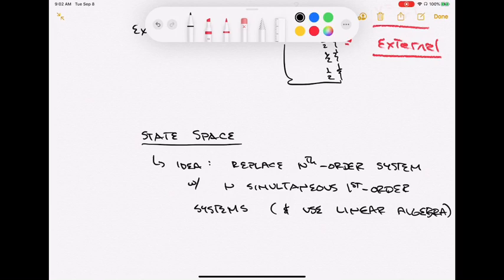Satellites and rocketry themselves are complex systems. You might be looking at differential equation models that might be of 100th order or even more. And dealing with a 100th order differential equation is hard. It is hard to deal with a single differential equation of a 100th order. Breaking that 100th order differential equation into 100 first order systems has tons of advantages.